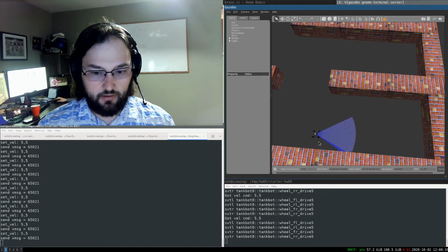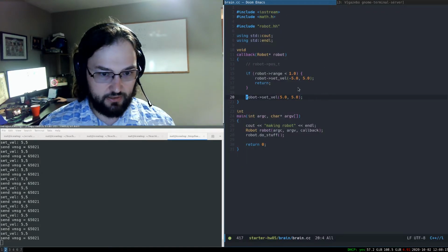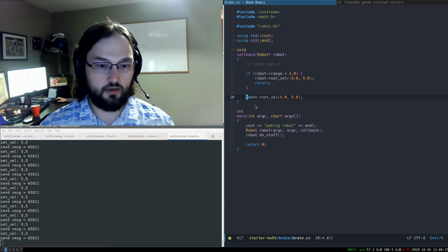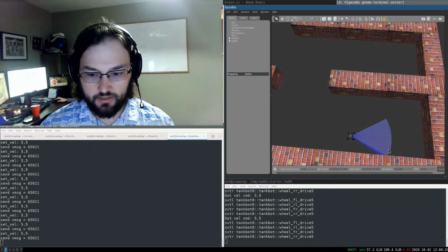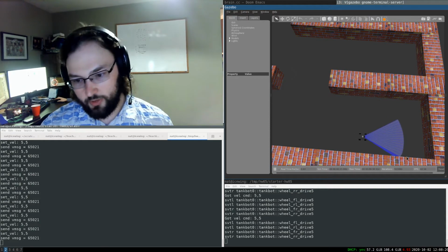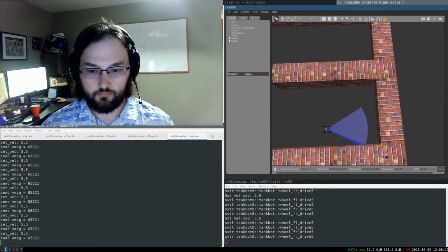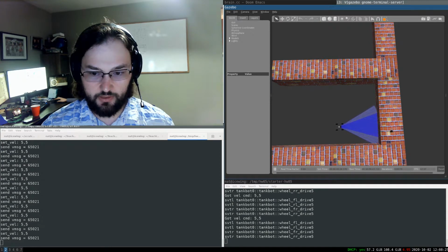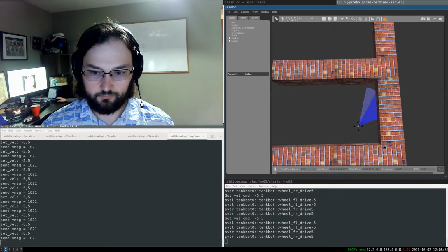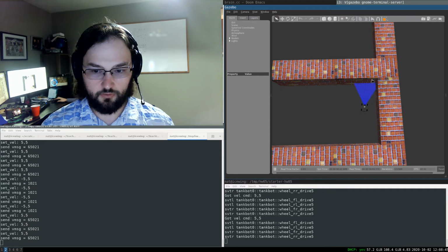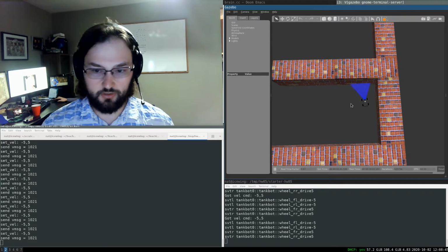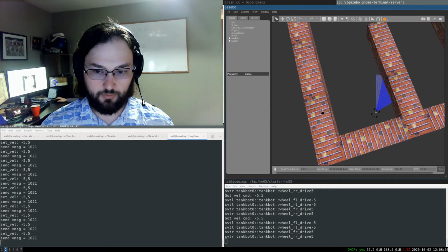So this logic that we have here of going to a fixed distance, so if we're less than a meter we turn, otherwise we go straight, is causing it to hold a fixed distance sideways from the wall because of this angle behavior. And then when we eventually hit another wall, we're going to turn. And so we follow walls when we have sort of convex turns here. But we have a slight problem.